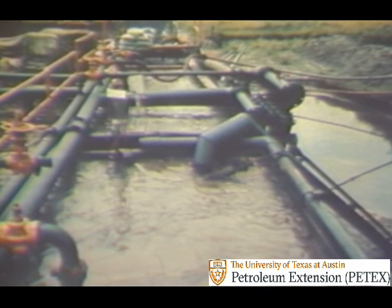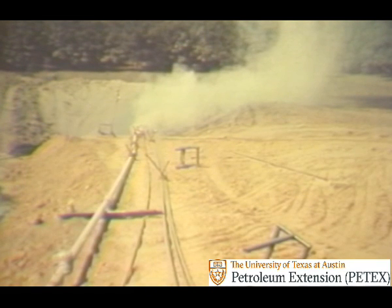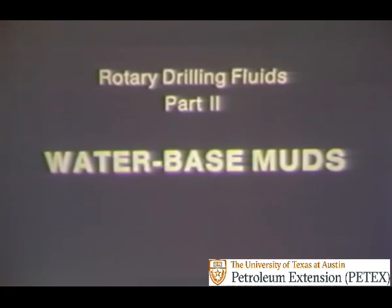So there are three basic classes of drilling fluids: water base and oil muds, both of which are liquid like the mud here, and gaseous fluids like air, gas, mist, foam, and aerated muds. Since most rotary drilling fluids are water-based muds, let's concentrate on them.